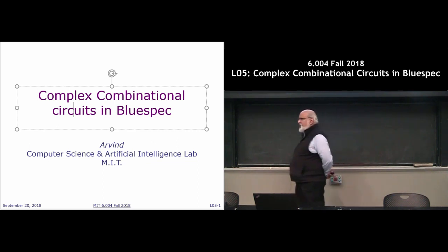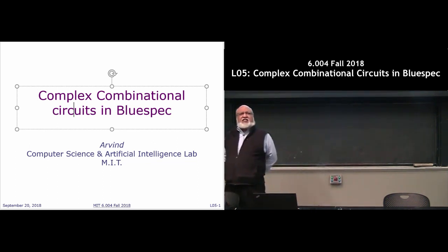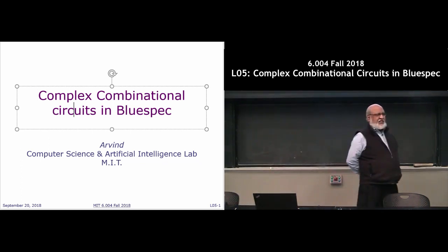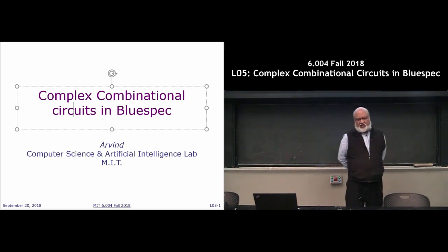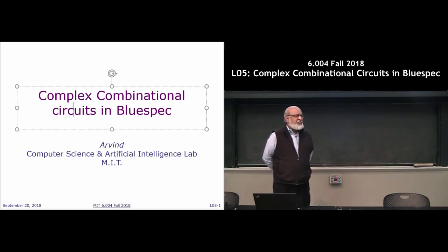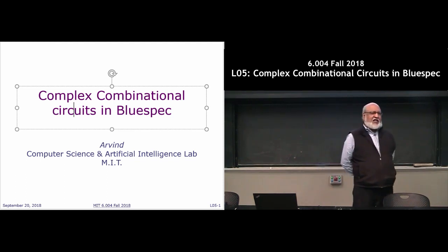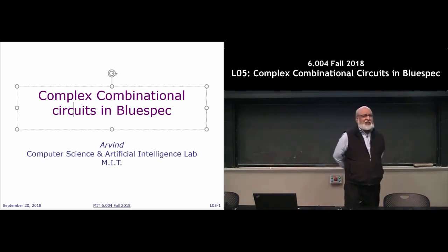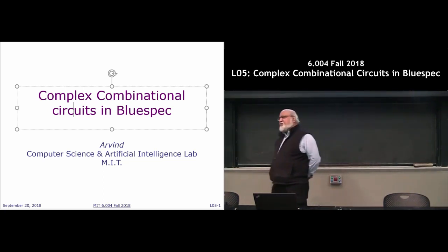Once you have done all these things, and you may have to do this repeatedly, it takes several steps, what you end up with is always an acyclic graph of circuits. What you will get out of it will be an acyclic connection of gates or some other operators at the bottom. Now this whole phase is known as static elaboration. And elaboration is a pretty good word here, because sometimes you will write very tiny programs and it can generate a gigantic circuit. So you have to be careful. It's always good to sit back and ask yourself, how big a circuit am I generating here?